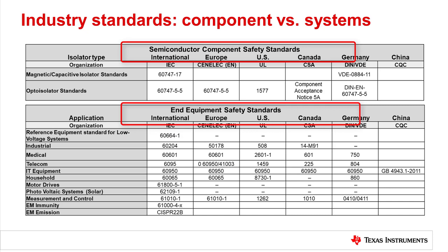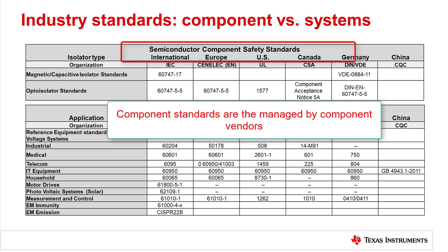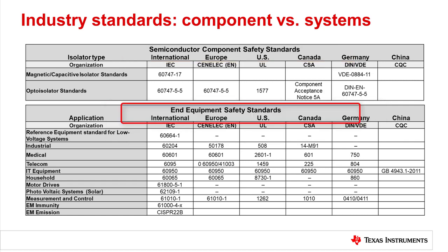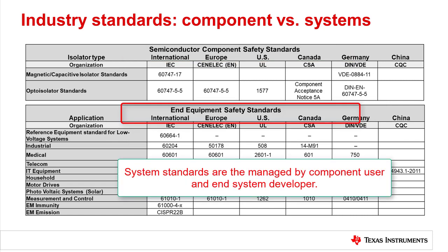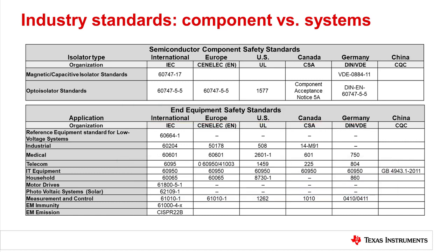Component safety standards are required to be met by the manufacturer of the isolation device, while end equipment standards are required for the user of the isolation component. In order to be considered reinforced, all isolator components, regardless of technology, must meet component-specific standards that apply to them, as shown here.